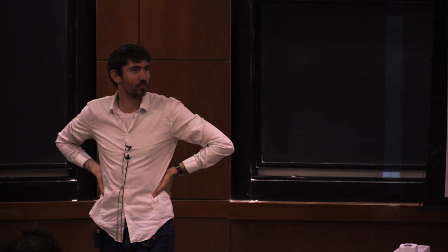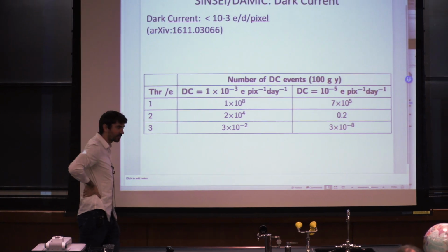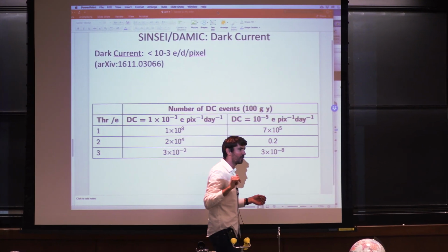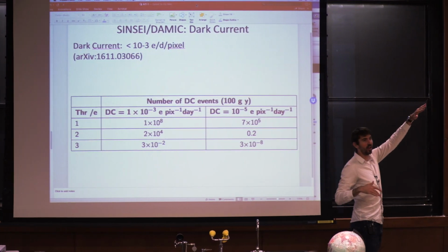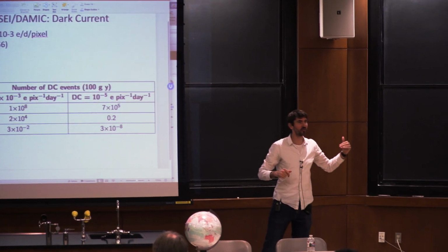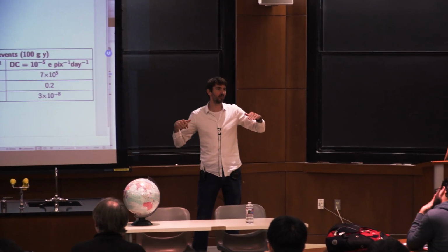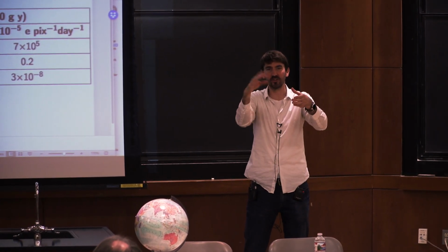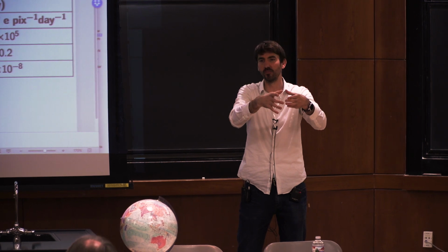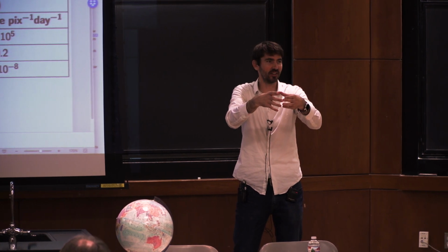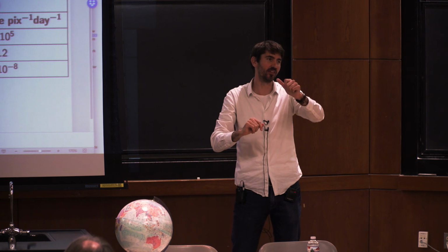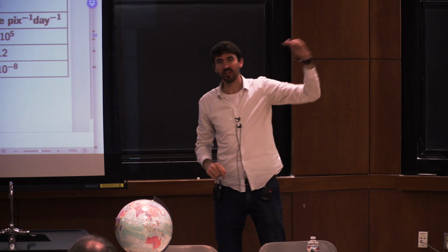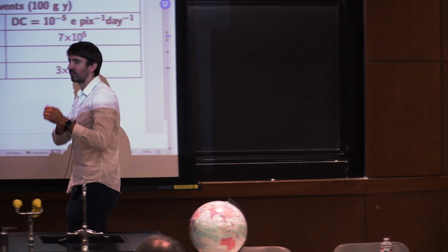1 over frequency? What is 1 over F? So 1 over F noise is just a lot of it. It comes from many, many different physical sources, but it's a noise which gets bigger the lower in frequency you go. So that's why this is a DC measurement. So you can't just let it sit there. In some sense, if you let it sit there and you measure 1,000 times, you would say, oh, I would improve my sensitivity significantly. Because of 1 over F noise, it doesn't. Your DC noise is actually very, very big. So you have to somehow break that.